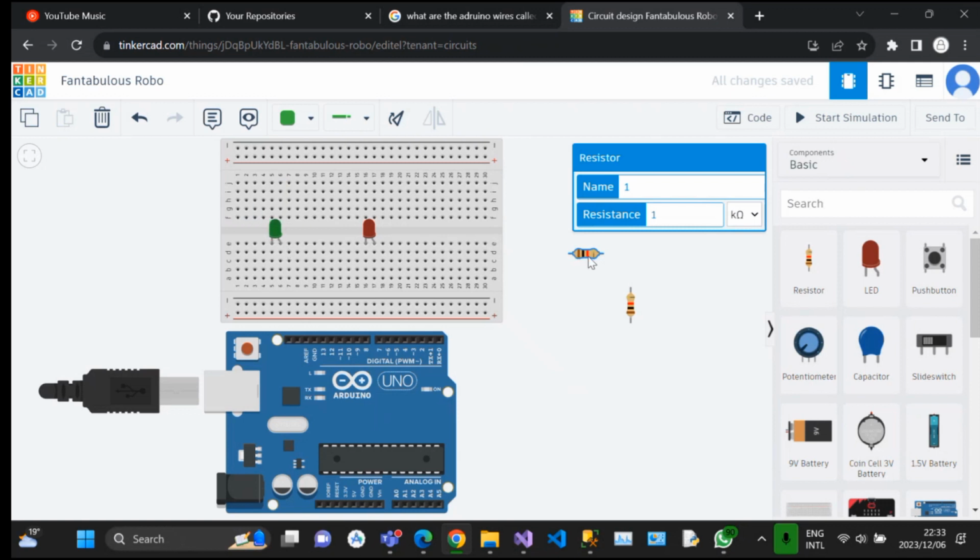So I'm going to put my resistor on the positive side of the LED. Same with this one, but I want to change the positioning to make it vertical. Yes, I connect it straight to the anode because these lines here go vertically, like this, and then these ones go horizontally.